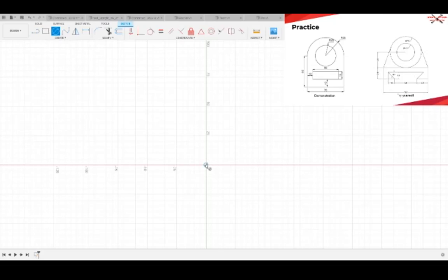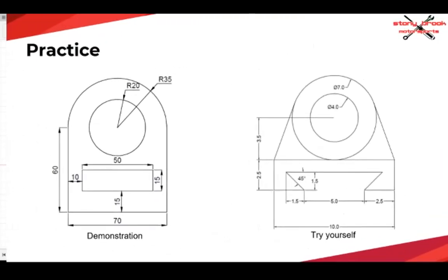First you want to actually define what portion of the geometry you want to be your origin. That is entirely preferential. Some people like to have their origin defined at the corner between two lines. Some people like to have their origin defined at the center of the circle. Personally, I go for the latter, because it's easier to set, since a lot of the dimensions on this drawing are relative to the center of the circle, as seen with this 70 millimeters here, for example, which is taken relative to the center line of this, though it's not marked.